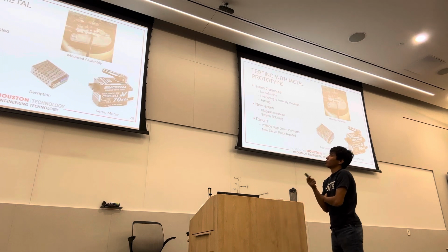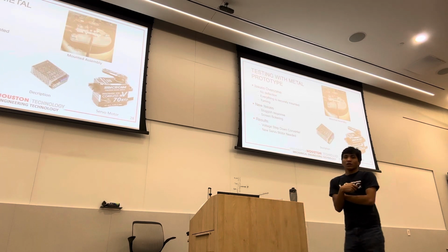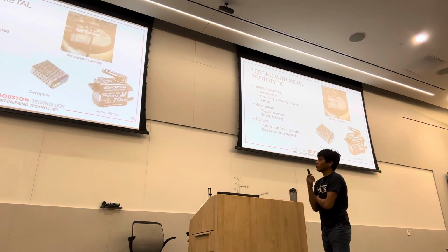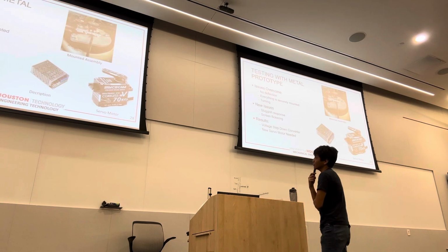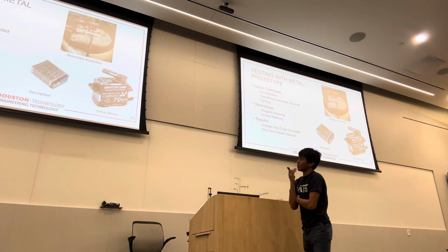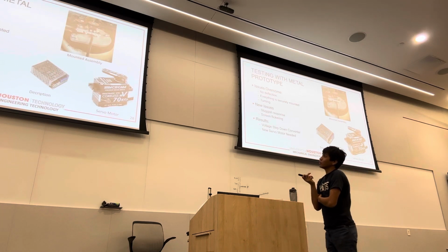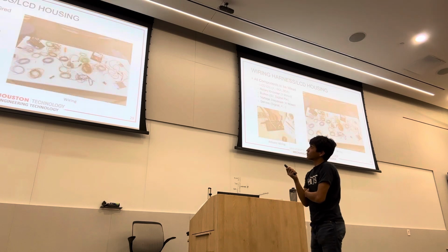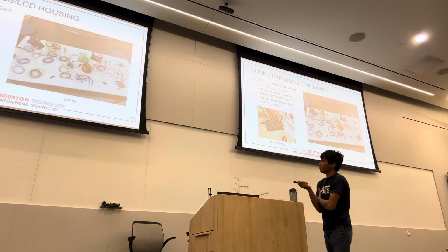And then from there, we powered the servo with the correct voltage, and it was still not as snappy as we wanted. So from there, we actually had to upgrade to another motor, and we did lose some degrees of turn with this, but we deemed it not worth worrying about. So the results: we got a new servo motor, and then we got the new step down converter. The wiring harness. So this was actually something I've done before, I've wired stuff before, I've repaired wiring.